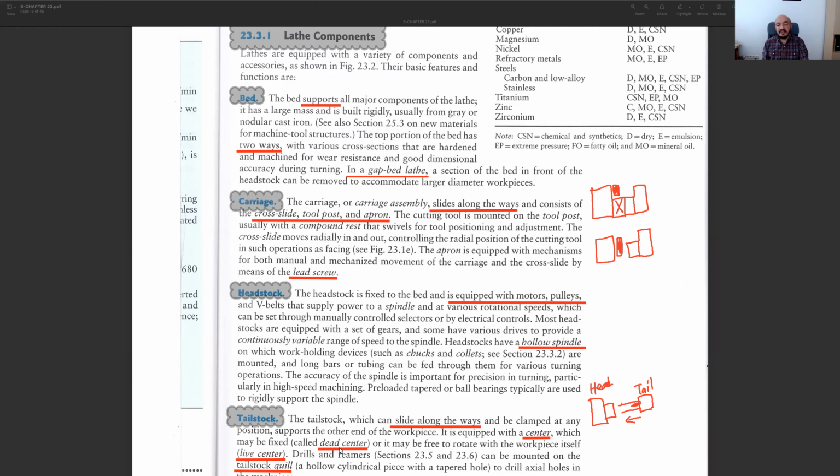And if you remember, I also said that for longer, thin and slender cylindrical parts, you may hold them from your tailstock and also from the spindle, obviously. With the help of it, they will be much more stable. You can decrease the amount of vibration and bending. But if it's too long, again you may have some rests, and these might be a follow rest or a steady rest. They are just used to make such longer parts as stable as possible.